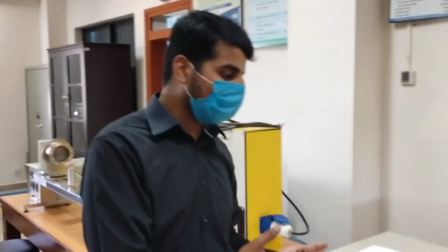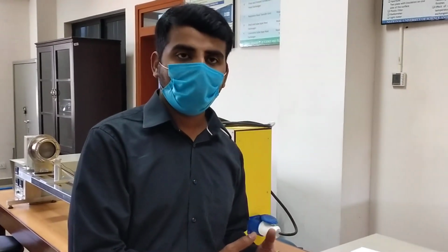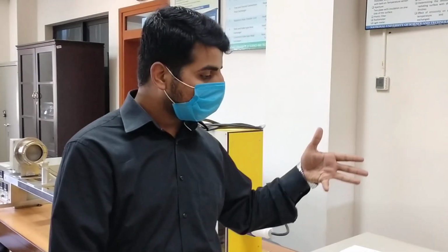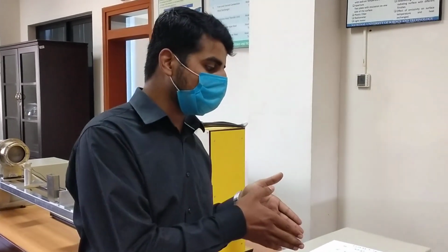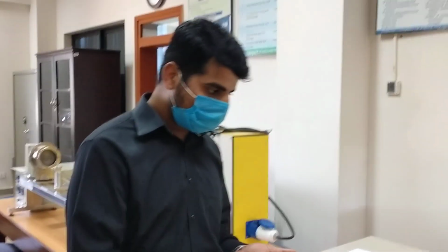Using those values you can analyze the data, and you can see how the heat conducts in the linear direction. You can observe the decreasing temperature as you go away from the heater section to the cooling end section, and you can also observe the temperature jump between sensors T3 and T4 and between T6 and T7. That's basically the outcome of these experiments.